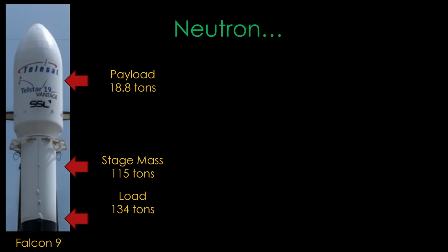It's actually worse than that. The booster gets close to 4 Gs of acceleration, so the bottom of the stage has to deal with about 500 tons of load. That requires a fairly beefy second stage structure.